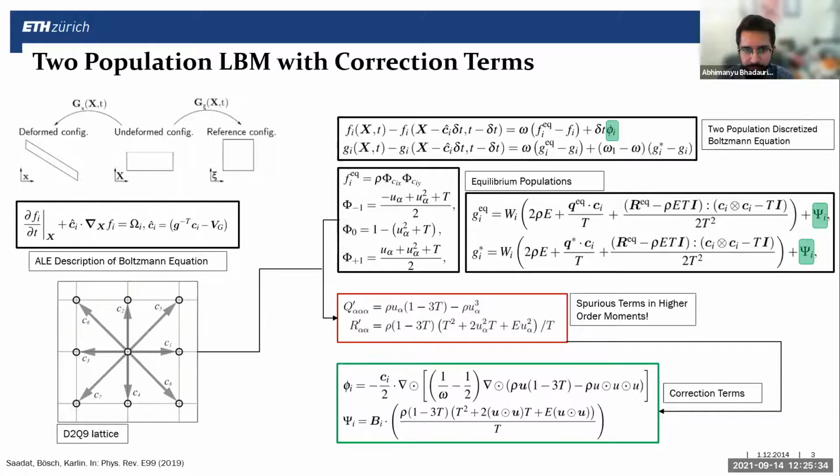If you look at the figure on top of the equation, we have all our simulations done on this undeformed domain, and we need a mapping. So we need this mapping G of X that goes from the deformed domain to the undeformed domain. Once we have this mapping, we can get these transformed lattice velocities Ci hat. Obviously, a drawback of that is that the lattice velocities are no longer on lattice, so we don't have integers anymore.